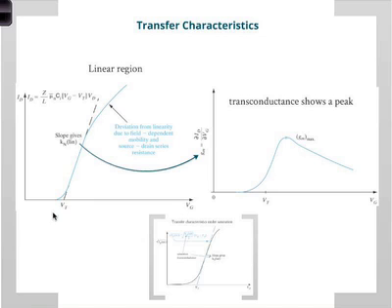And we know that when the gate voltage is below threshold, there's no current because there's no channel. At some point, it will start going up a little bit, and that's the so-called sub-threshold region, which we'll talk about later. And then after threshold, it forms a linear region. This is where strong inversion happens, and pinch-off has not happened. So you have a channel, and saturation has not happened. So this is the linear region. Then after a while, some kind of saturation happens. Saturation, of course, happens with respect to the drain, but with respect to the gate, you get some additional nonlinearity, which is shown here.